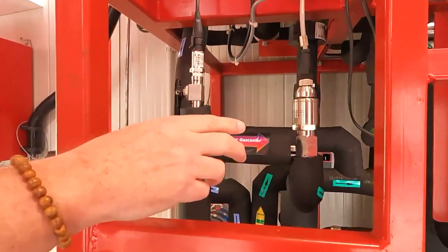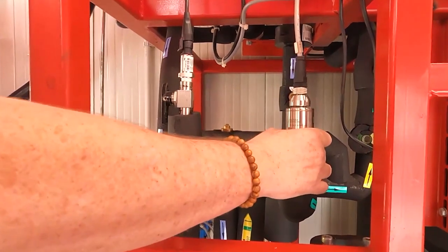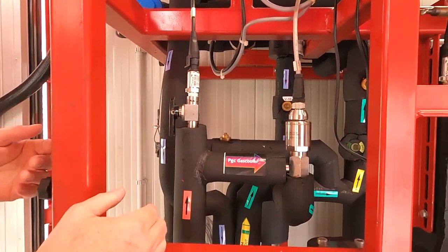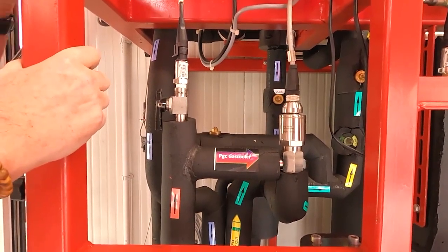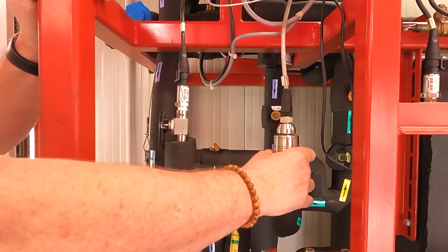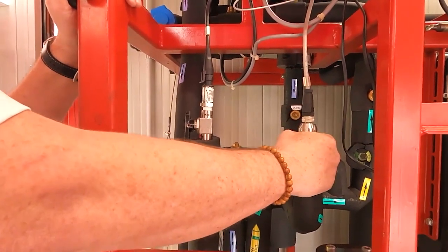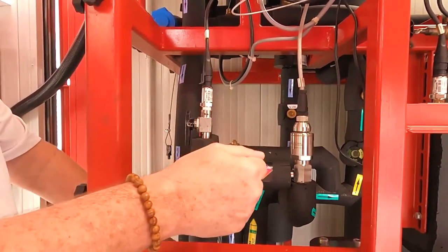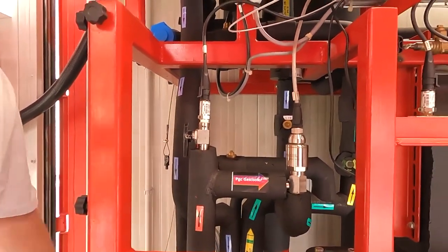One thing I'll note, I mentioned earlier that you don't have to have both of them. There is some benefit to having both. In a low ambient condition on an ejector block, they're not equal stages through the different nozzles and ejectors, but you're only going to get maybe a combination of 15, 16 steps from the ejector block. Here you've got 2,500 steps on the high pressure valve. So for low ambient, it does kind of make sense to have the high resolution of the stepper valve. And then when you get above a certain ambient, move over to try and get your Venturi effect, pull the trigger on the pressure washer wand, pull that load up to your parallel compression temperatures. I hope that answers the question.